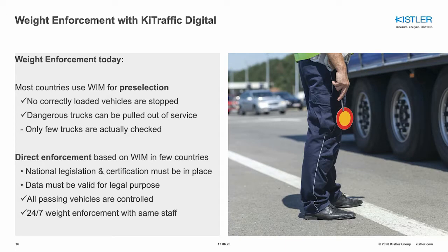Few other countries already implemented a direct enforcement weigh-in-motion approach for weight enforcement. There, the national legislation is already in place, and a certification on how to approve WIM systems to provide legally relevant data is also established.